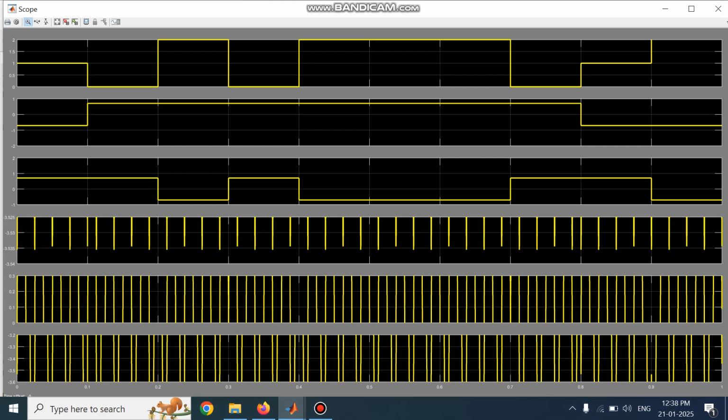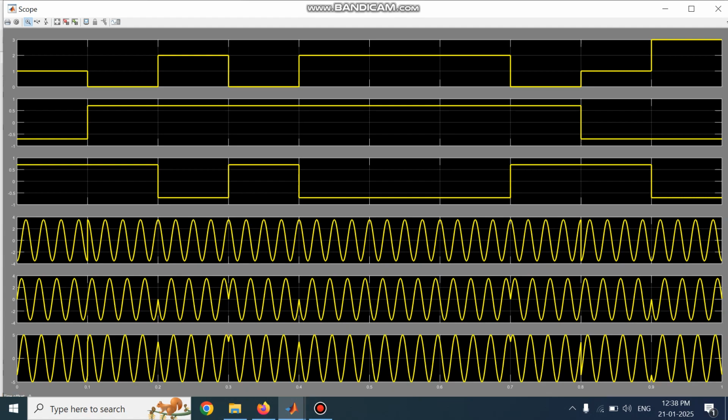So this shows the waveform. Here, this fourth and fifth waveform represent the BPSK output at the output of the in-phase channel and quadrature channel. Now here, the initial odd bit is 0. It is represented by minus cos. And here, the odd bit is 1. It is represented by plus cos. So here the phase is 0. Similarly, at this point there is a transition. This is 1 and this is 0. Therefore, here there is a 180-degree phase shift. So this is minus cos here.